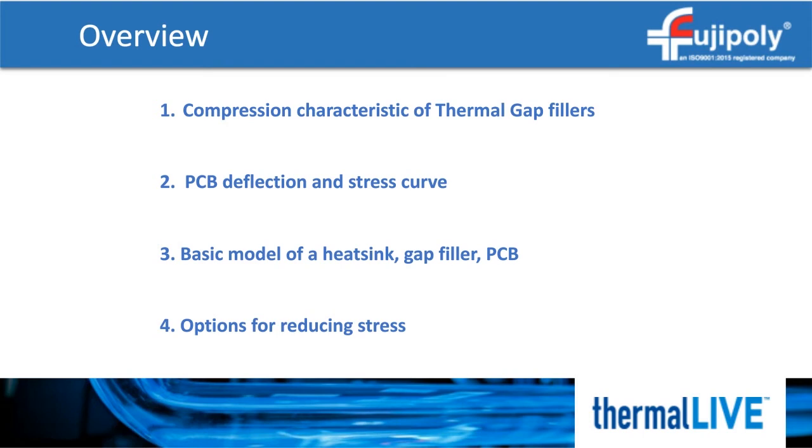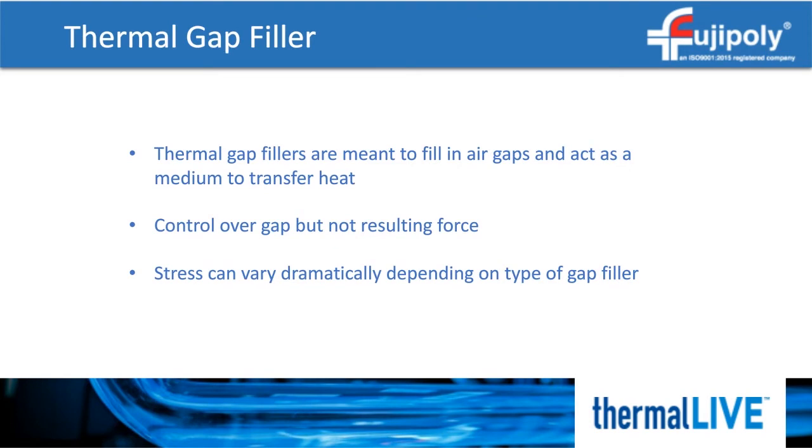Whenever we discuss thermal interface materials, it's always good to define what exactly is a thermal gap filler. Thermal gap fillers are a thermal interface, but they're unique from something like a phase change or a grease. In the case of phase change and grease TIMs, these are basically designed to reduce contact resistance only. A thermal gap filler is designed to fill in a gap that can vary due to tolerance.